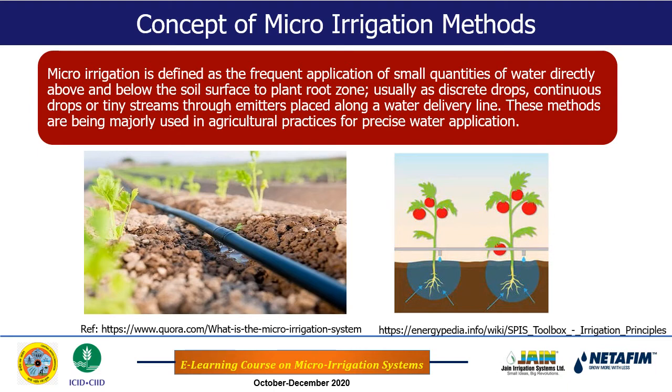If we shift to the sprinkler irrigation method, it is actually possible to apply even 2 mm, 4 mm of water in one application. But the frequency of the application will be once a day and so on, and for that we have to design the sprinkler irrigation system in such a way that it will be expensive as well.